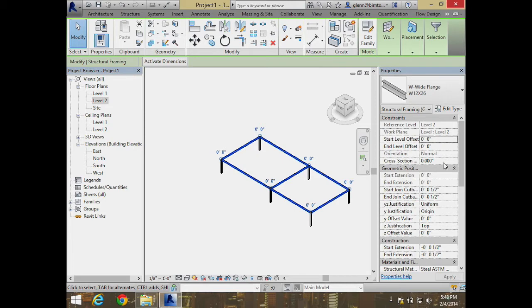It's not a very good way to do it. I'll show you a better way in just a minute. You can make a sloping beam. But if I want to just have them all drop down, I'll use the Z offset. It'll just drop it straight down. And that's where, in our case, -5 inches will do us a good job.